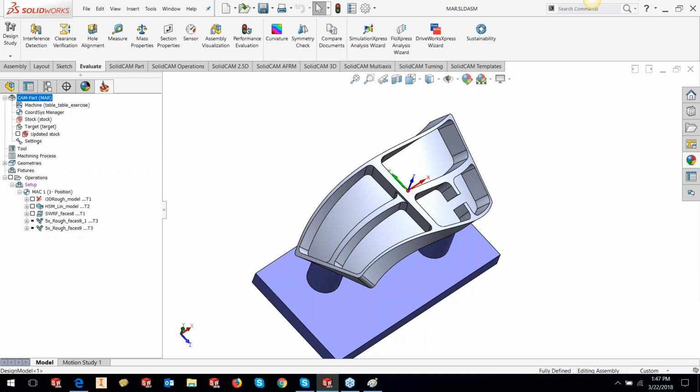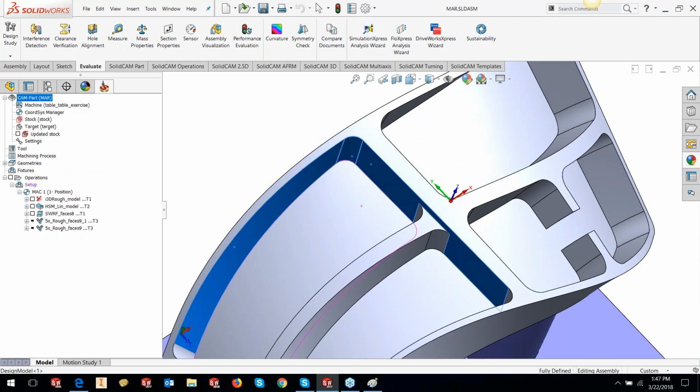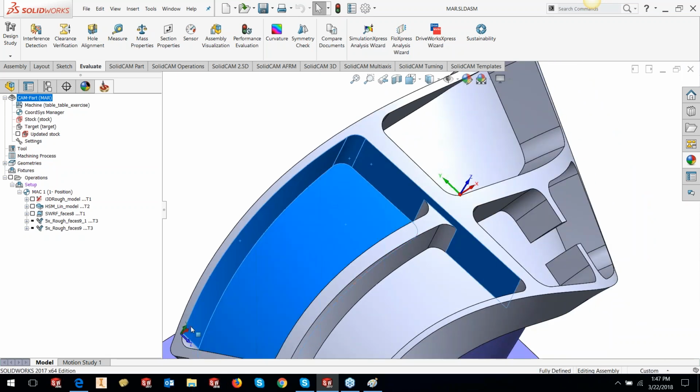Multi-axis roughing works on a very simple principle: the side surfaces, the flanks that it needs to cut, should be normal to the floor surface. If they are not normal to the floor surface, then it will leave material from those surfaces. It will not cut the exact surface. These surfaces, which we call wall surfaces, should be normal to the floor surface.